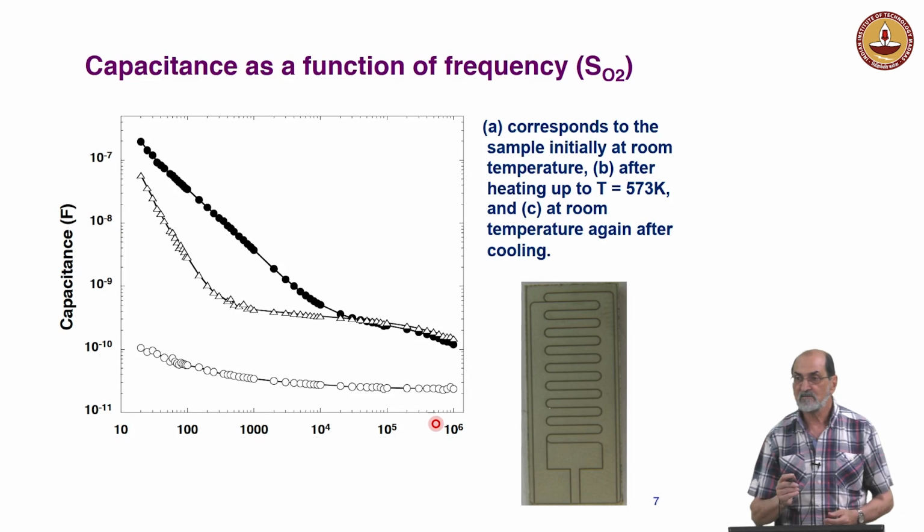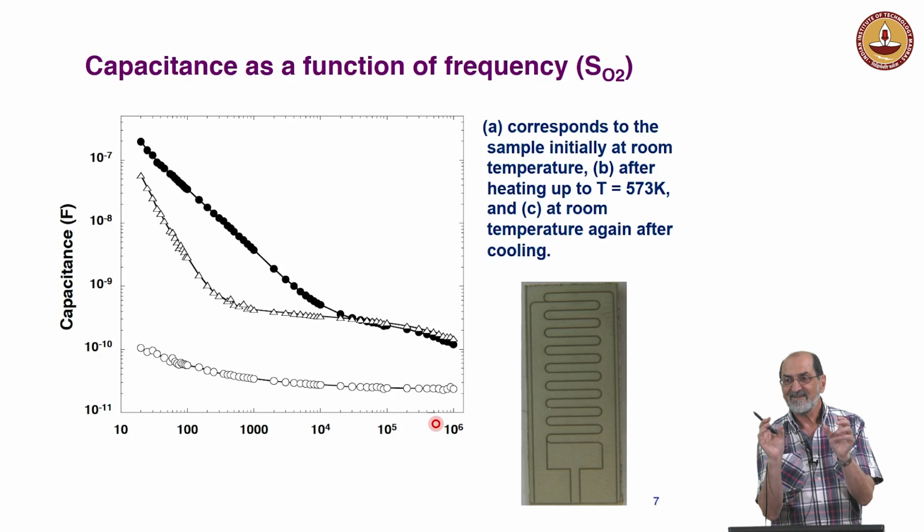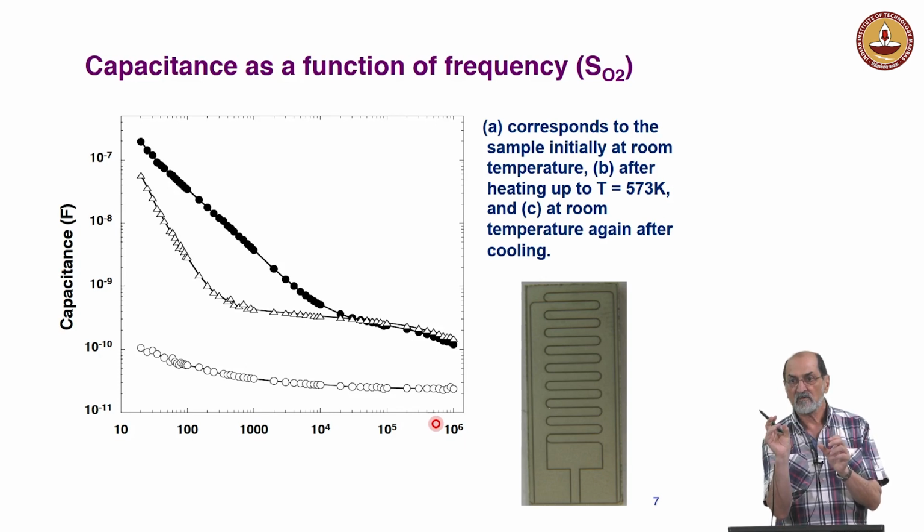Do you understand that? No. Did I explain it well? No. When we have a Schottky barrier, as the Schottky barrier is narrower, the distance is like a capacitance of plates. It's like the plates are closer one to the other. See? As the doping increases, it's like the distance between the plates is smaller. If that's the case, the capacitance is high.